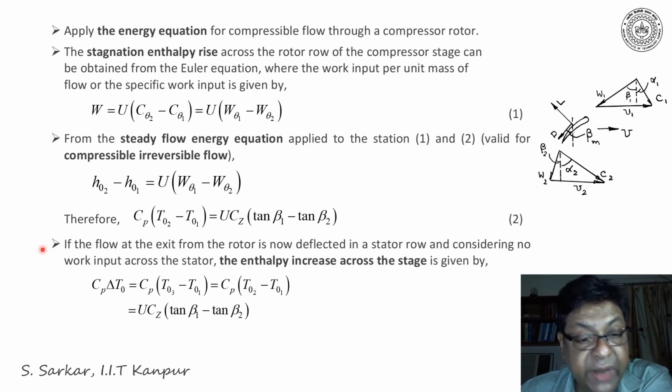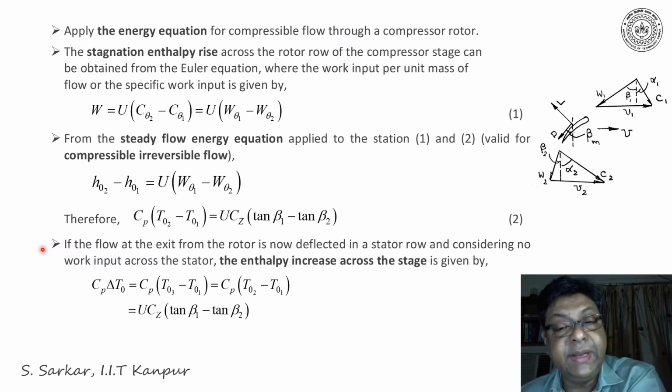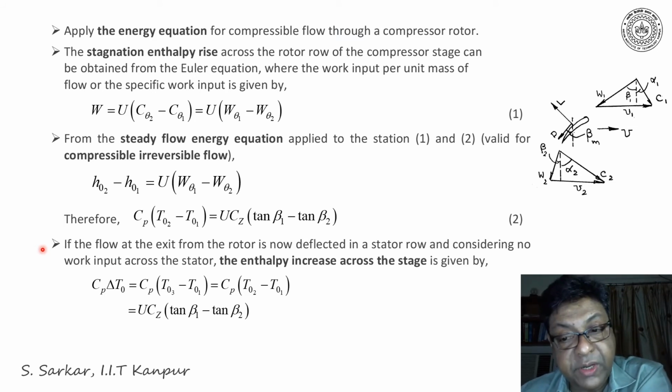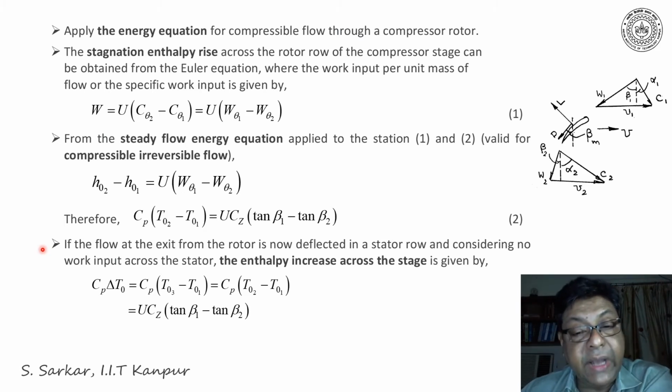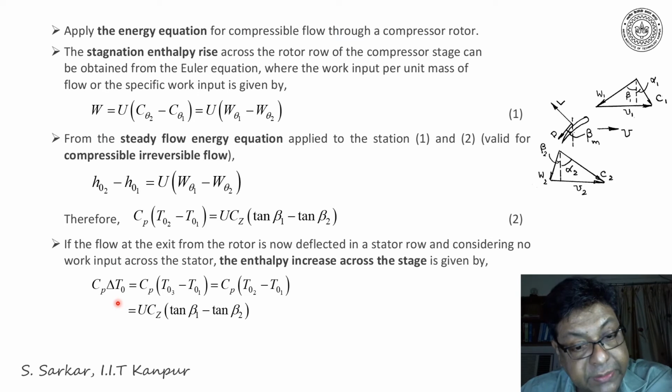Now please note that the flow at the exit from the rotor would be deflected in the stator blade. However, there will be no work input in the stator. Therefore, the enthalpy increase across the stage would be Cp into del T0, where del T0 is the temperature rise